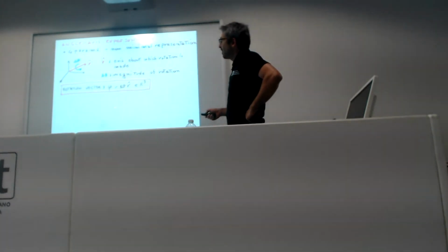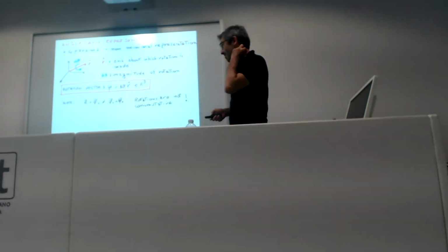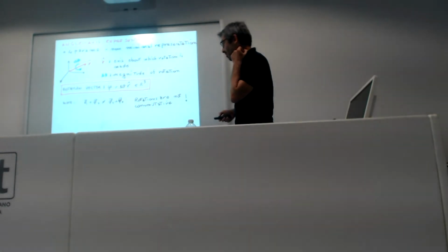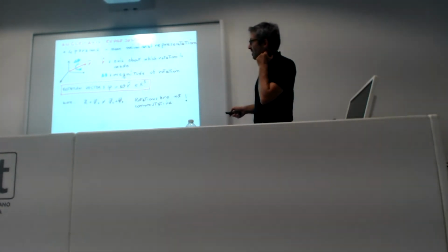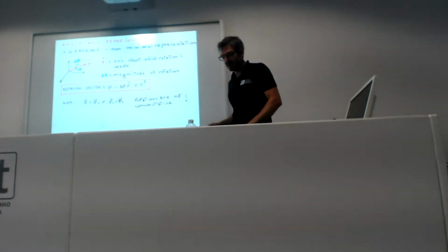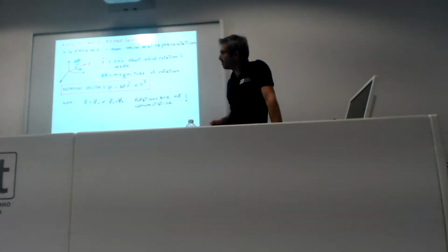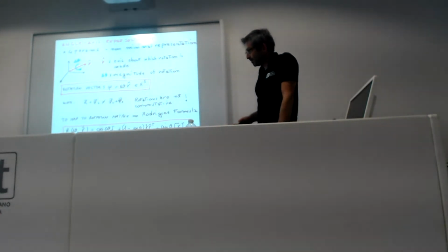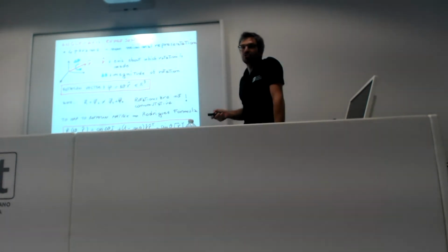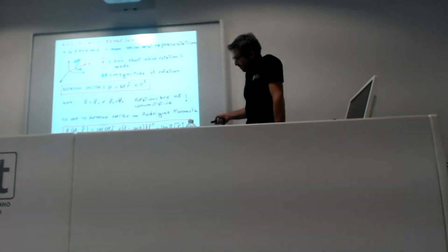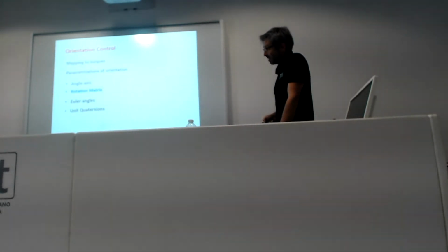If you multiply both, you get a rotation vector. It is a Euclidean vector. Of course, rotations are not commutative, so summing them is different than swapping the addends. If you want to map this angle axis into a rotation matrix because you need to do some other calculation, you can use the Rodrigues formula. It's just a complement.